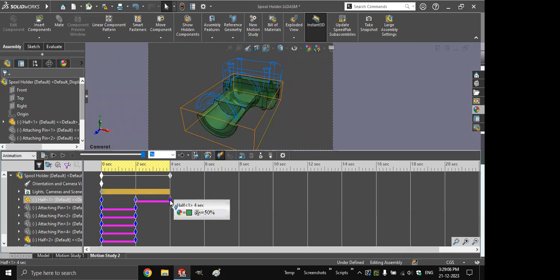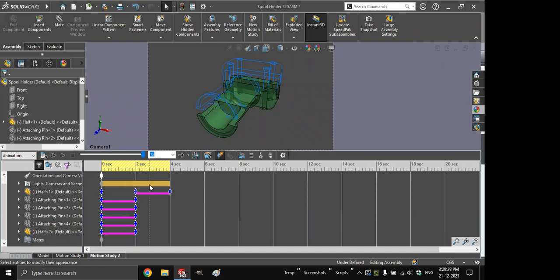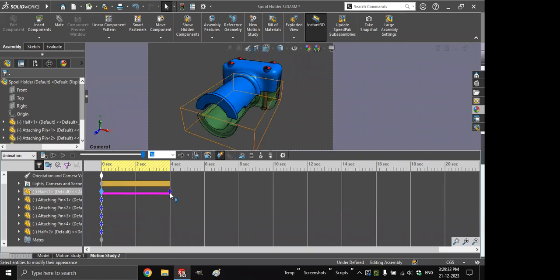So with that key point, as you can see, it shows me that the appearance is going to be green and the transparency is 50%, while over here, the appearance is blue and the transparency is 0%. And that's the change that happens over here. But before I start moving to another topic, let's just remember that this actually might happen a bit quick. So let's say I want this transition to be different. So to make that easy, let me just turn all of these off. Let's just focus on this one. All right, so I'm just changing it from being blue to being green and changing the transparency.